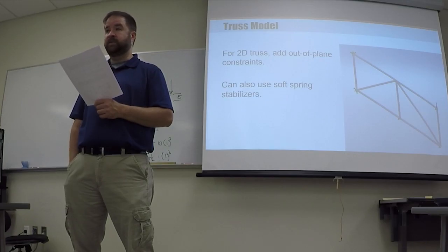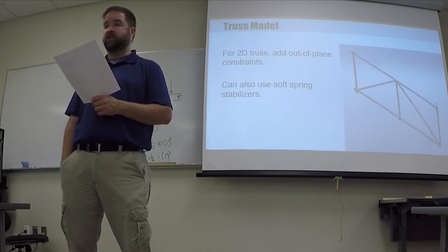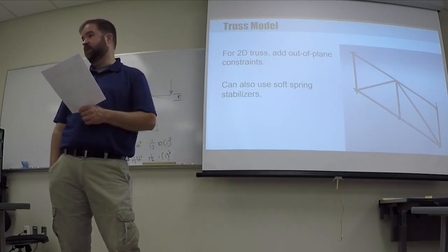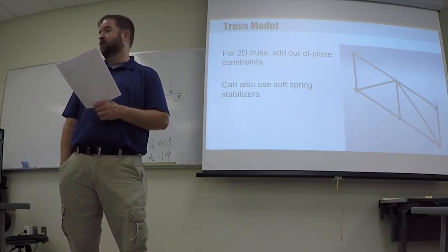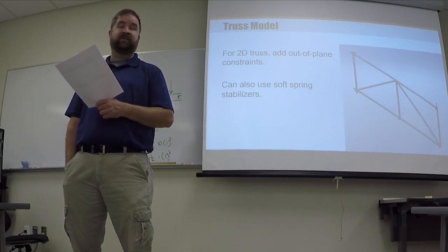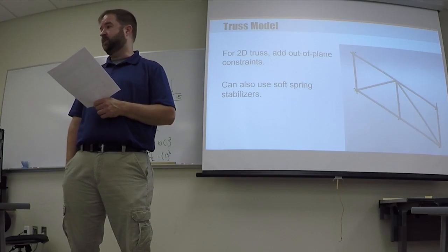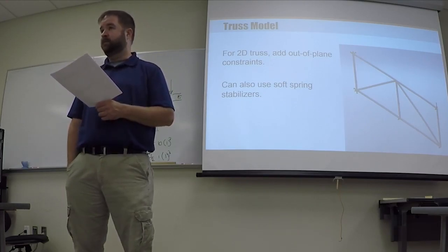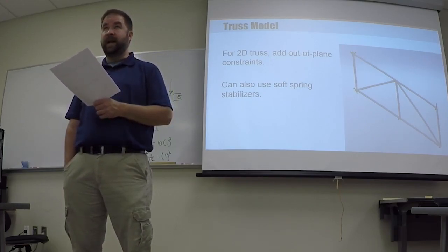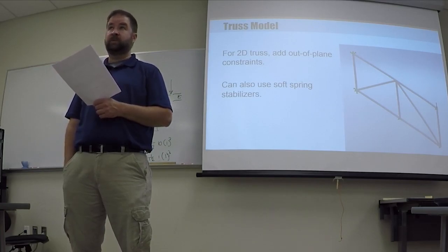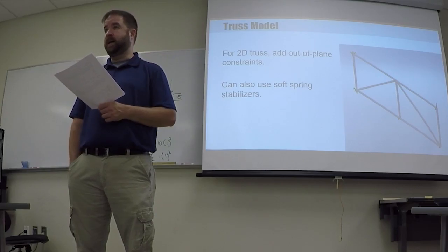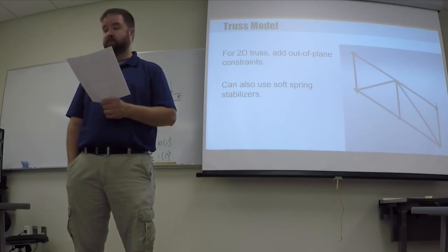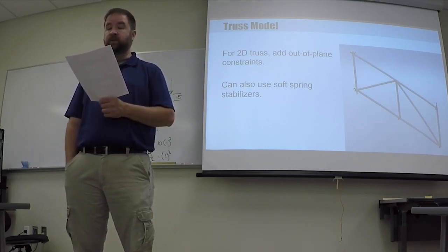Then do two elements, each of them 25 inches long, and one of them is going to be 7 something, the average of 10 and 5.5, so that's 15.5, so that would be 7.75. And then the other one would be the average of 5.5 and 1, which would be 6.5, so that'd be 3.25. Okay, see where we're going with that? Then do 4 and then do 8.